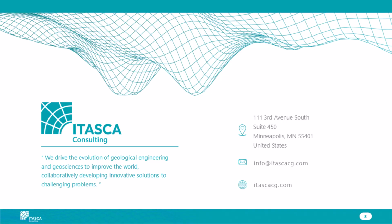So what is the best way to ensure that the input ground motion is applied correctly in a seismic analysis when using a compliant base? I mean, there are different ways that you can do it. I prefer to extend the depth of the model all the way down to a layer that I can consider bedrock or close to it, so that at that point, I wouldn't need to do a deconvolution.